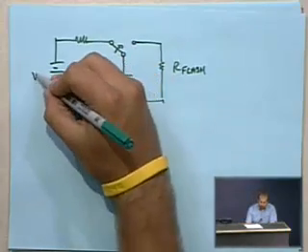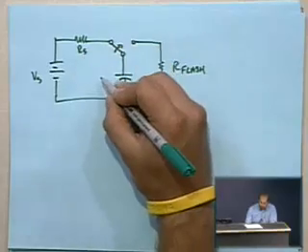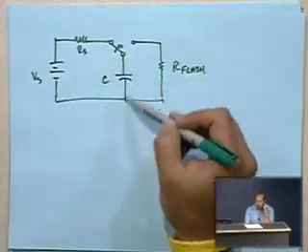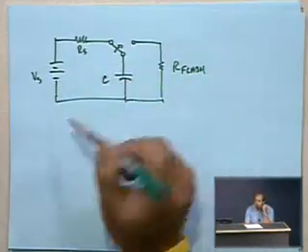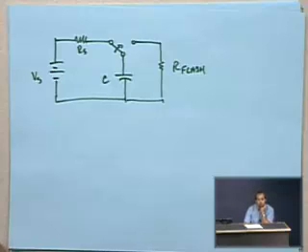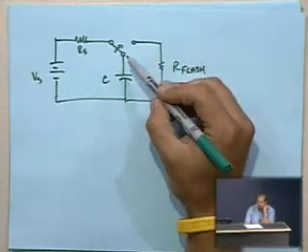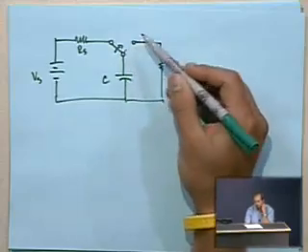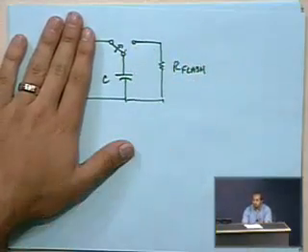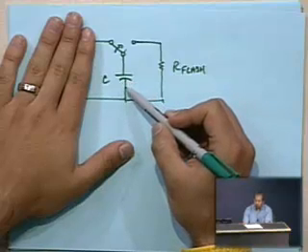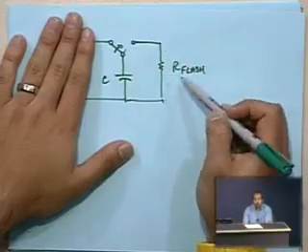So again, this is the battery, this is just some resistance, and here's the capacitor. Current will run around this loop in the circuit until the capacitor is charged. Once it's fully charged, it becomes an open circuit. It stops drawing current from the battery, and it will sit there. Then once you press the shutter button, the switch moves over to this position. The battery is isolated from the rest of the circuit, and all of the voltage across the capacitor will now discharge relatively quickly across the flash.